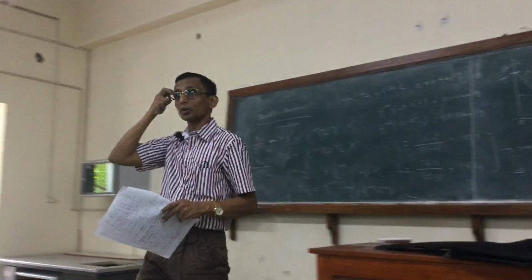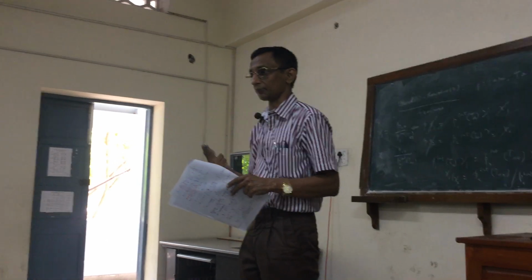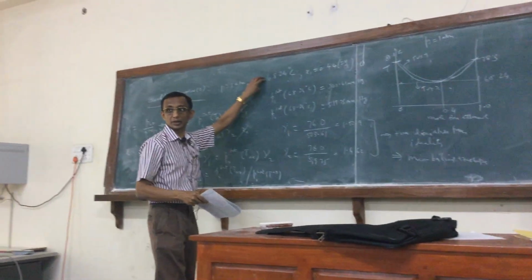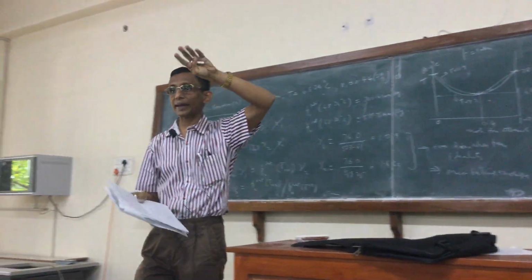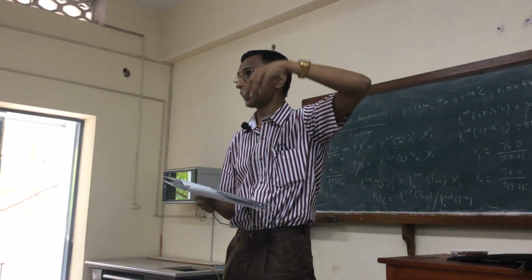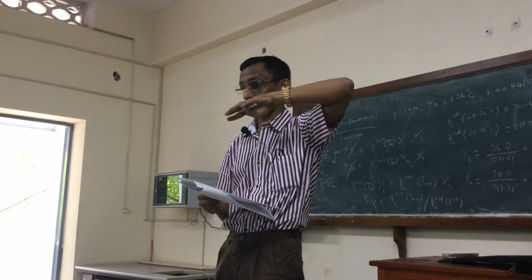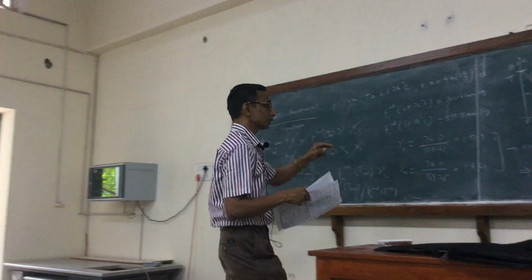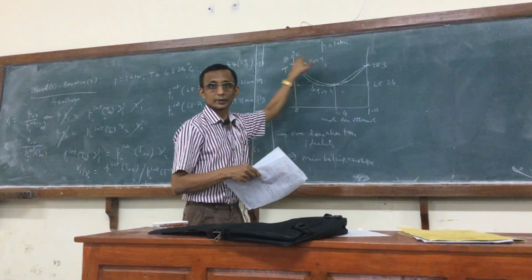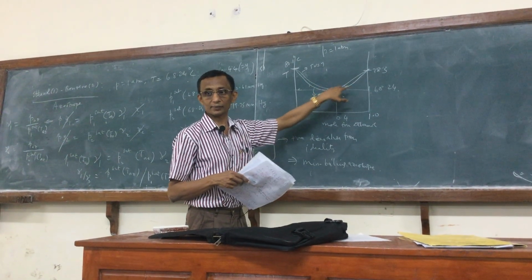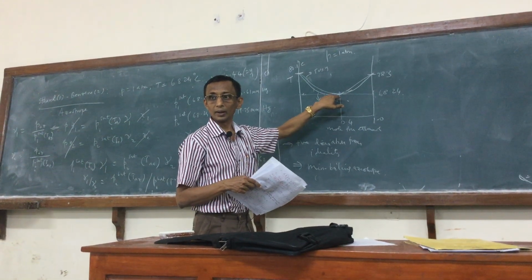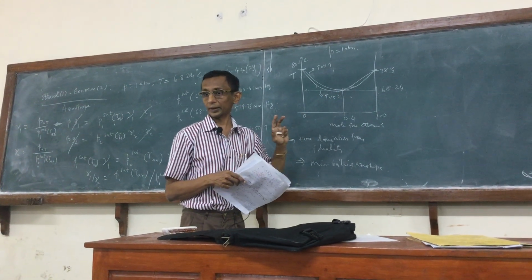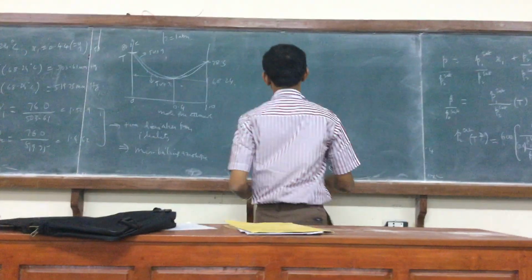What is interesting to know is that if I now construct a phase diagram at constant temperature, namely the azeotropic temperature, the pressure versus X and the pressure versus Y curves will exhibit a maximum at the azeotropic pressure. There is a correlation between them. It can be theoretically proved that for both the temperature curves, T versus X and T versus Y, if one undergoes a minimum, at the same point the other will also undergo a minimum. That is the azeotropic point. Right? So X1 becomes equal to Y1. That can be established here.